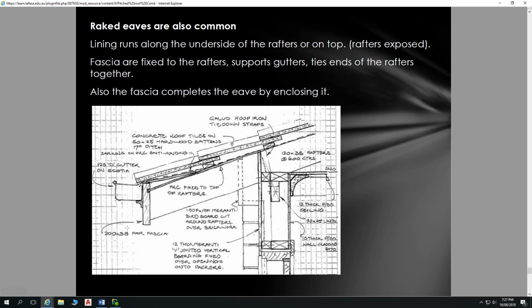A few details in here that you may not see on all roofs, and this is a very good detail. So an anti-ponding board there to stop that. We've got sarking over our roof, and that sarking is carried under our battens in this example. That sarking fixed under battens is a good idea because it provides plenty of space between the sarking and the tiles. So sarking requires that bit of space to work properly to enable getting rid of moisture, so ventilation,